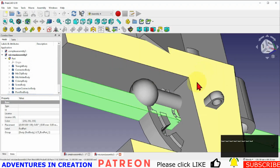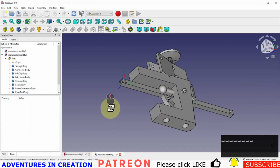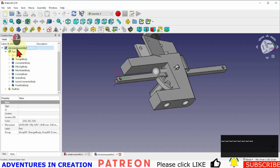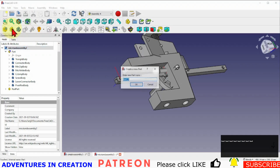I mentioned that once you create all these bodies, you can change it and put them into parts, and we need them all to be in parts to be able to import them into our assembly. So to do that, we are going to create new parts. We're going to say create a part, and we're going to call this triangle body.